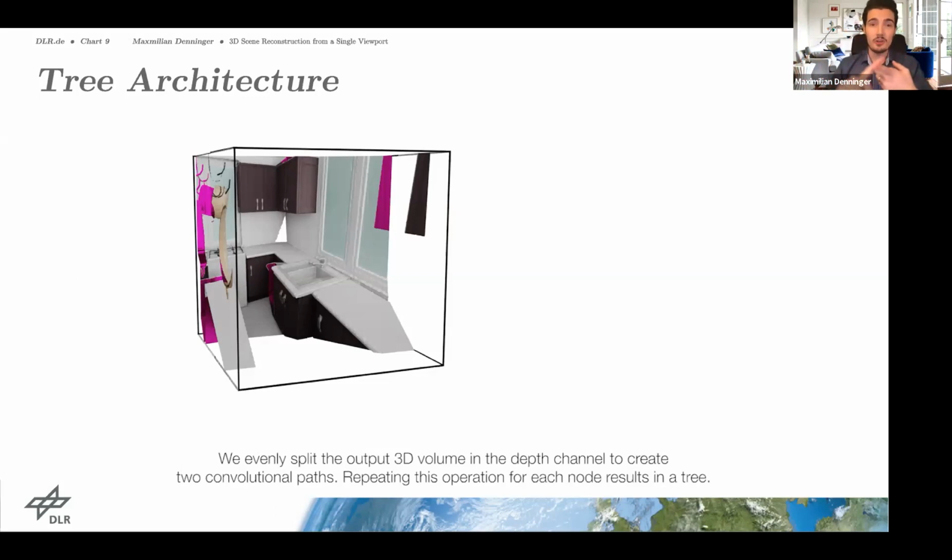Of course, you could use TOF, time of flight, which sends out a signal and then waits for the signal to come back. Depending on the surface, this might not bring anything back if the surface is quite dark, or it is shiny and you don't get any useful information back. So there are always difficulties with depth cameras. Of course, this could help here.